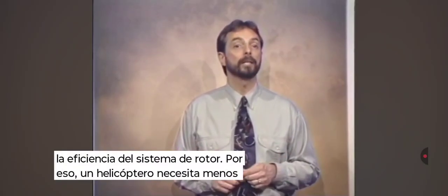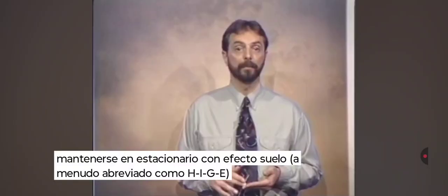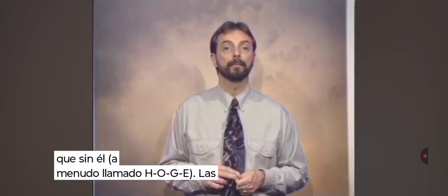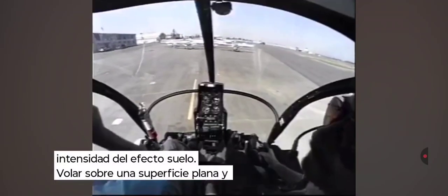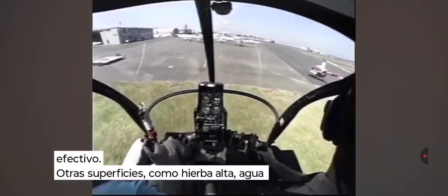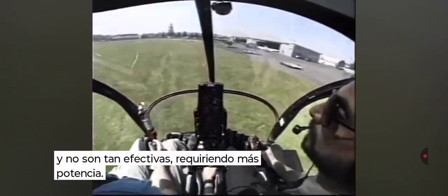That's why it requires less power for a helicopter to hover in ground effect, often abbreviated HIGE, than it does when out of ground effect, often called HOGE. Different surfaces influence the intensity of ground effect. Flying over a flat, hard surface works best. Other surfaces, such as tall grass, water, slopes, dissipate the static air pressure and aren't as effective, requiring more power.